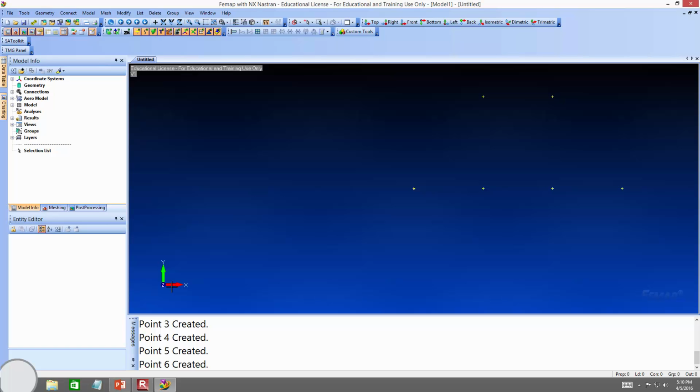Well, no, okay, that's a good question. Do we need to start over right now? No, we don't, okay? And I'll tell you why. Like I said at the very beginning, what unit system does FEMAP use? The answer is, it doesn't use any units. You just need to be consistent, okay?